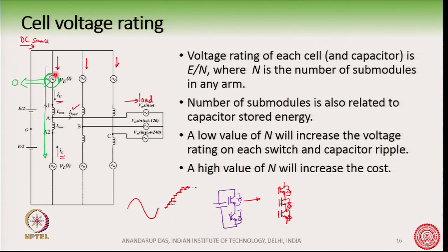We know that when a single phase current flows through a single phase voltage source with a phase difference between them, the power has a DC component and a second harmonic component.